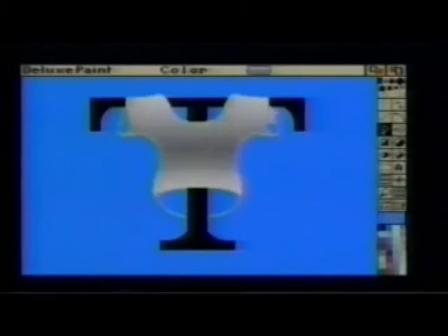Click the right mouse button on the current color box to change the color palette. Any one of the 32 displayed colors can be changed from a palette of 4,096 by moving the slider bars. By clicking a color, then spread, and a second color, a smooth transition between the two is created. Now click Range and a color, and the gradient color fill range is changed. An unwanted fill can be stopped by pressing the space bar.